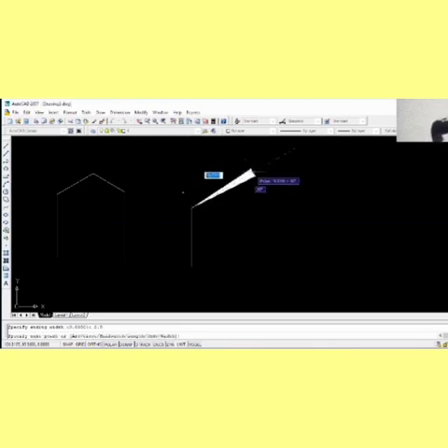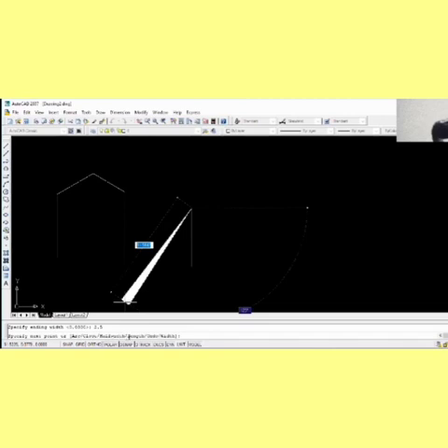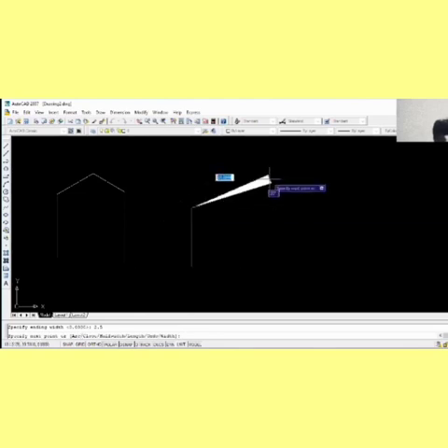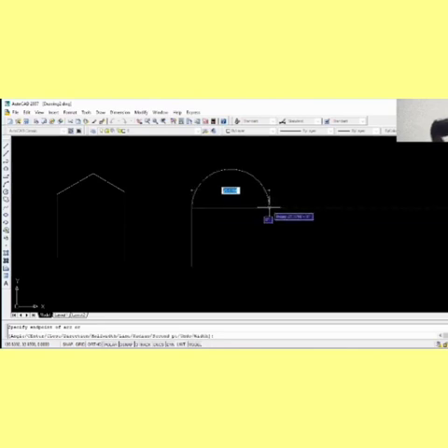And then now I can decide to form an arc here. So if I want to form an arc, you can see here, I have arc, close, half width, length. So let me choose an arc. So if I want to choose an arc, I can just choose the first letter here, which is A. And then I choose A, enter. So now I can click here. Remember, I already chose the starting width as 0 and then the ending width as 2.5. And I also chose an arc. So I click here, and that is the shape we have.